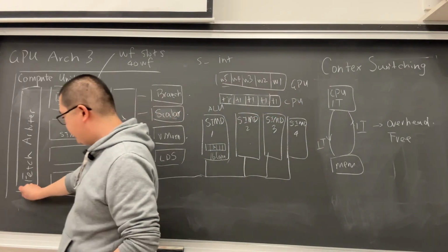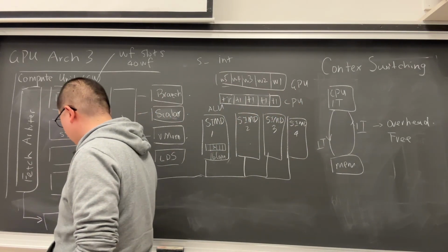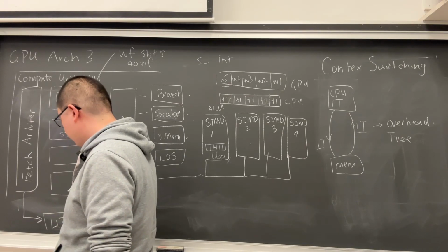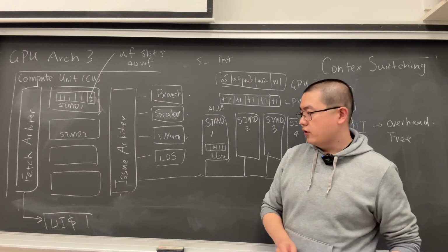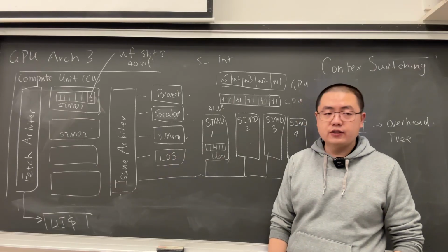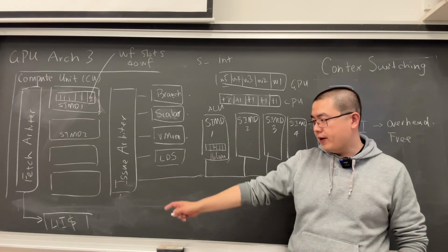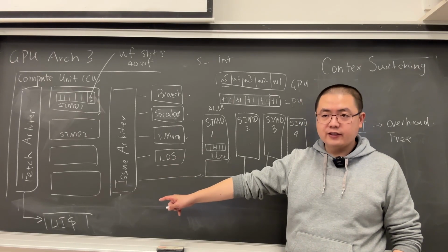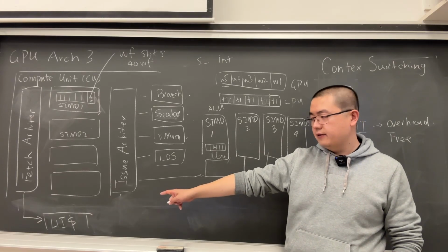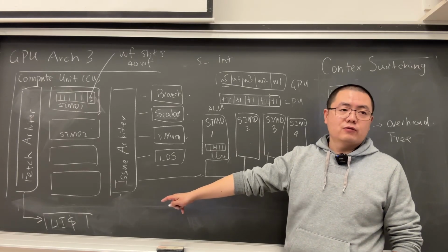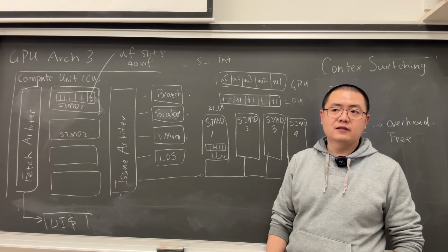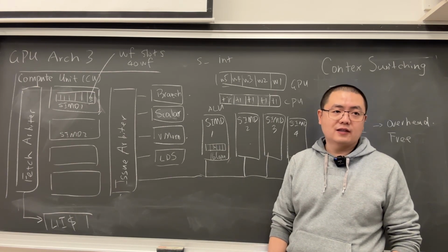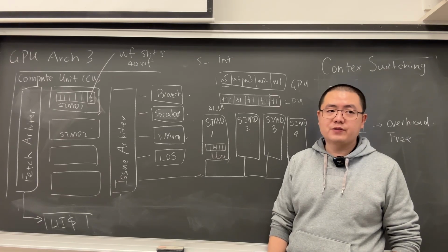If you talk about sharing, or how we can reduce the overhead of fetching, fetch is connecting to the L1I instruction cache. Okay, so the fetch arbiter is connecting to the L1I cache. The L1I cache is super fast, and what's the likely hit rate? It's pretty much always hit, other than the first time miss, right?